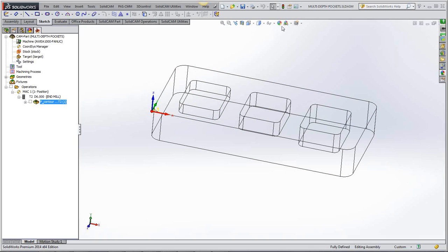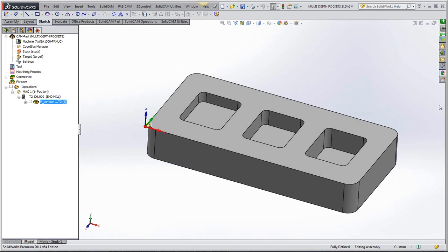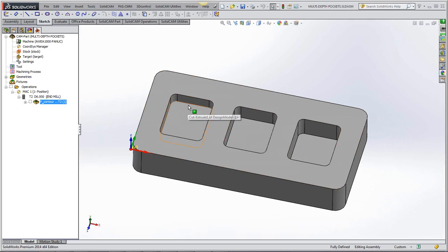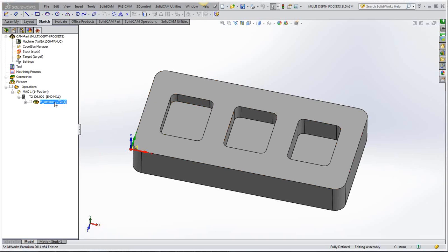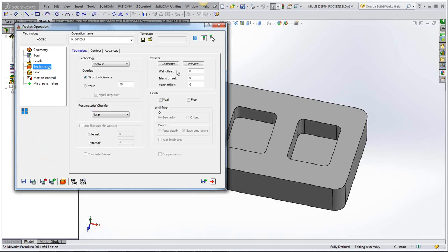Okay, another little thing we can do on this model whilst we've got it open is we have the ability now, as I said, to change the offsets of that geometry and finish it. As I said previously, you couldn't finish a geometry in a pocket that was larger than the actual drawn geometry. But now, as I hinted earlier on when I had this open, you can do that. So if I once again open the technology menu there and have a look inside there, you can see we have this extra little tab here of geometry offsets.